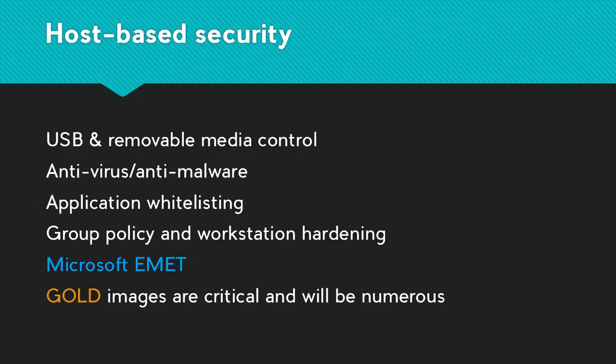Group policy and workstation hardening. Again, similar concepts to enterprise IT, just done a little differently. You're probably not going to be able to enforce a screensaver timeout of 5 minutes with a password required to unlock it again. You push that out to an HMI, after 5 minutes all the displays in the plant go blank, and you've got an incident.